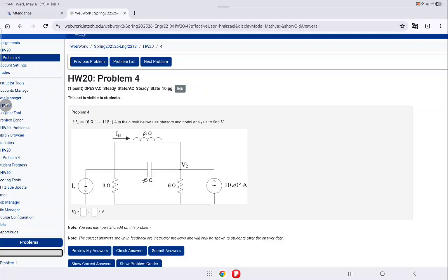Then still you have 2 nodes, so you can't do nodal. Do a source transformation, you get 1 loop. That's it. Okay? Just do transformation to the left side. You don't need to do it for the right part as well, because it will still give you 1 equation, 1 unknown.